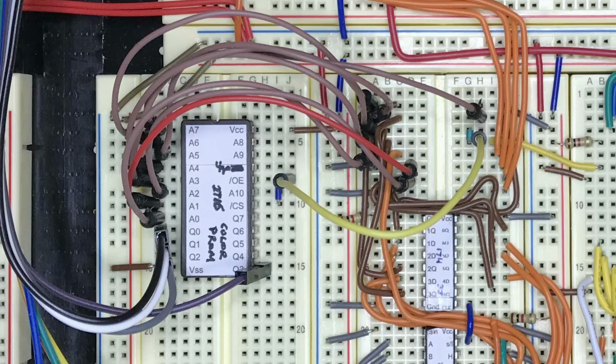Earlier in the video, I suggested that it's quite difficult to get the small color PROM chips programmed due to the old technology they use. I wanted to see if we can replace that PROM chip with a more typical EEPROM, like the 2716 we've been using for the character ROM.